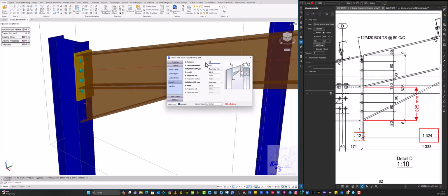And then we go to erection tolerance. Erection tolerance usually varies with standards and codes depending on which country you're from, but I'll say 2 millimeters is safe. So you can put 2 millimeters on either side of your rafter.